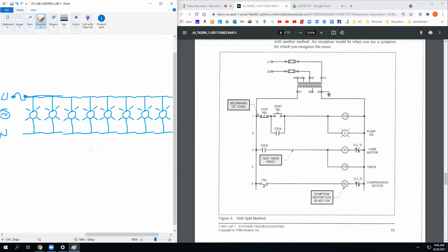And you're given this problem to troubleshoot. That fuse keeps blowing. What do we do? First of all, why would that fuse blow? There's a ground fault somewhere, right? On the line side, there's a ground fault somewhere. Correct? The neutral is tied to ground.